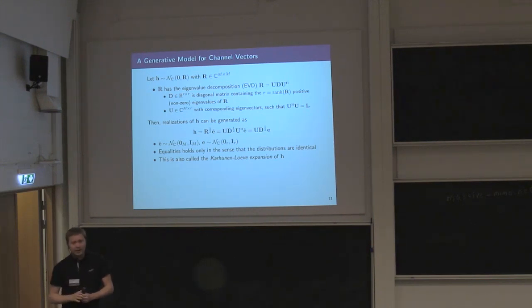Yes, so in theory a lot of people have been preferring to work with IID Rayleigh fading models, and the reason for that is you can get all these nice expressions that Eric was describing. Then there is probably no real scenario where you have exactly uncorrelated fading. In some cases you might be close to it, in some cases you will be far from it.